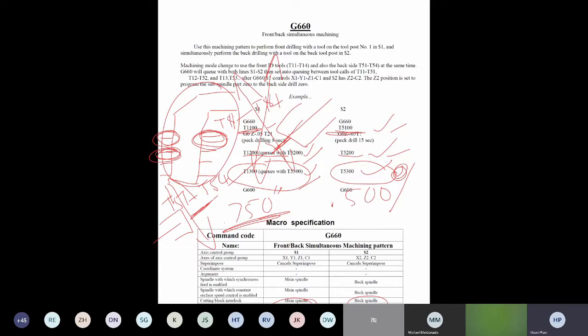So if you jump to the next tool right here, that means the X-axis is going to raise up, and this tool right here is still following in the sub spindle. It's going to break the tool right away. So that's one reason why we cannot use the tools unparalleled in this mode.